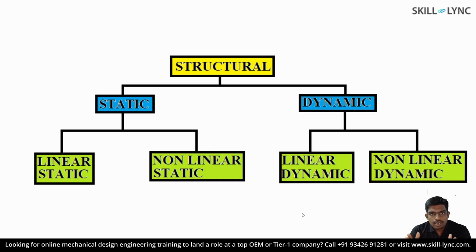Basically, a structural analysis problem can be classified into static analysis and dynamic analysis depending upon the loads that are acted upon. Apart from this classification, we do have 1D, 2D, 3D finite element analysis that is classified based upon the element that is used. We have several other specific analyses like buckling analysis and fatigue analysis, which serve the purpose that they were designed for. So SolidWorks has separate modules for each of the special analyses. Now let's look at the basic classification of analysis, that is static and dynamic analysis.